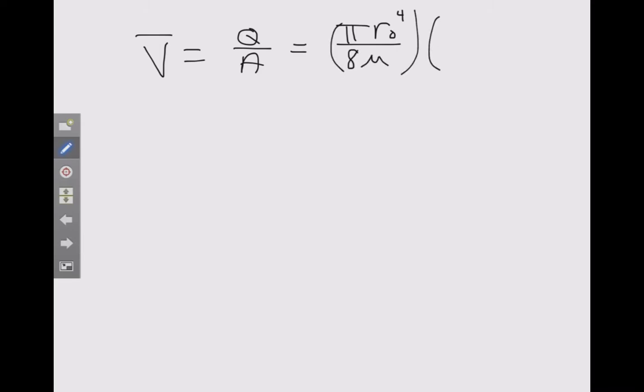If we actually go back and compare this to the Vmax, if we determine the average velocity now as this equation, which we've used before, we've got pi R0 to the 4th over 8, gamma delta H delta L, and if we divide that by the area, which is pi, the total cross-sectional area of the pipe is pi r squared,